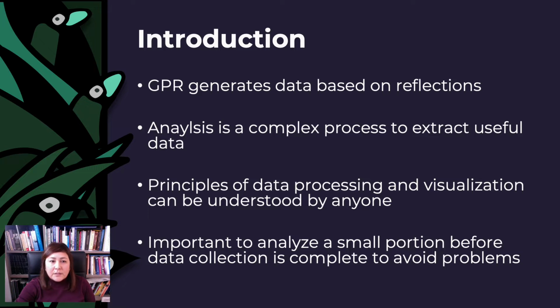Often processing is conducted after data collection is complete, but it is also advisable to process and visualize a small portion of the data as a pilot step in a GPR project or even during data collection, as this will allow for early identification and prevention of problems in the data collection process.